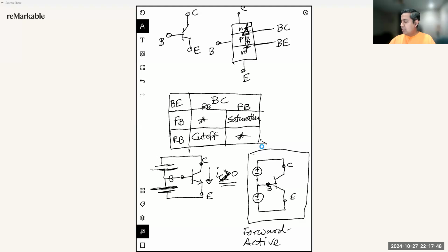In this region of operation, the BJT will be conducting, because we have forward biased the base-emitter junction, similar to the saturation situation. There will be a huge flow of electron carriers from the emitter to the p side of the base. But unlike the saturation condition, we have reverse biased the base-collector junction, but current will still flow because of the high density of electrons in the p-type region.